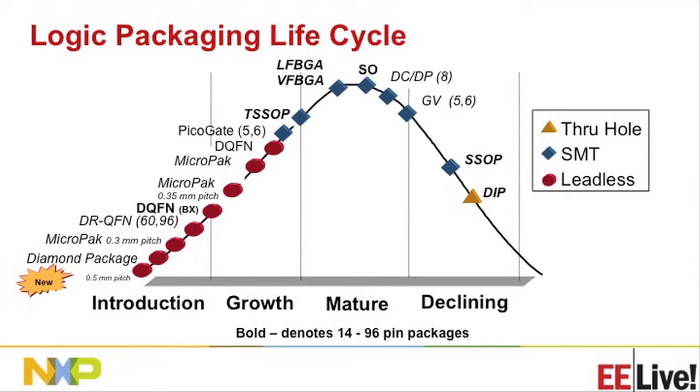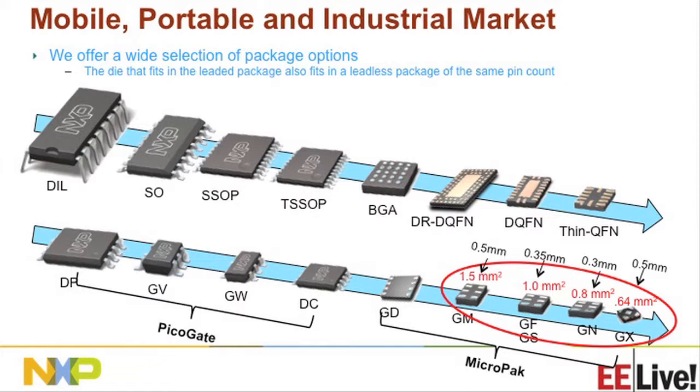And then on the trend, you would see the DIP packages on the right-hand side, which are being phased out or in discontinuation phase. So if you look at the packaging evolution, this is a DIP package. Probably before I was born, like 40 years ago. The top row has evolved into smaller leadless packages, but they are more than 4 or 5 functions in one device. So the trend is to go leadless, and today it's at BGA or QFNs.